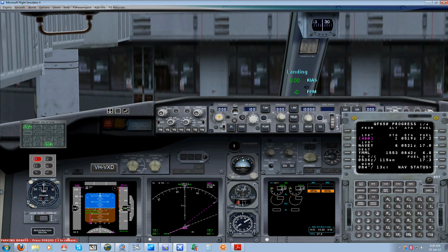Now if there was a major wind change in here, before you actually depart, make sure that you check the ATIS again, and you may have to just quickly program the FMC for the wind change for the runway procedure. All you have to do is go back into departure arrival, click on departure, and select the different runway that you need. Same again, you would go back through here, select the runway, select the SID and click execute, but we don't have to do any of that because we're still using runway 21. So that's the end of the FMC.